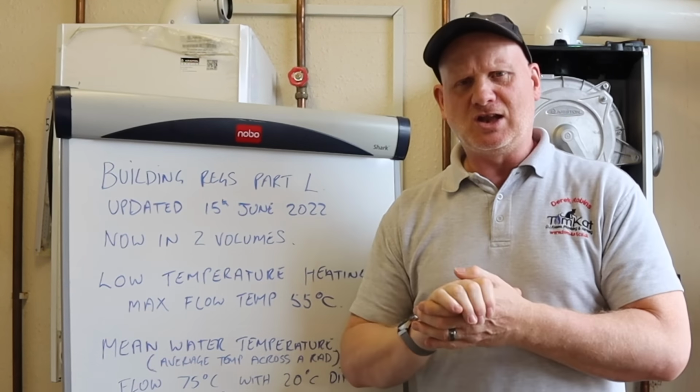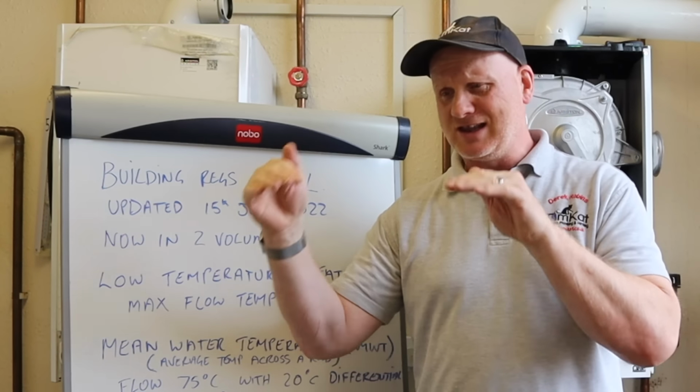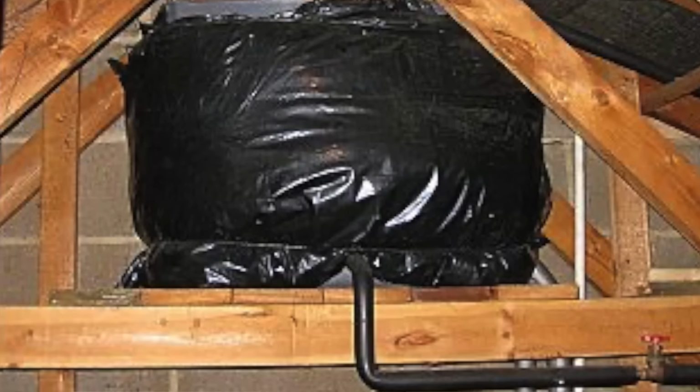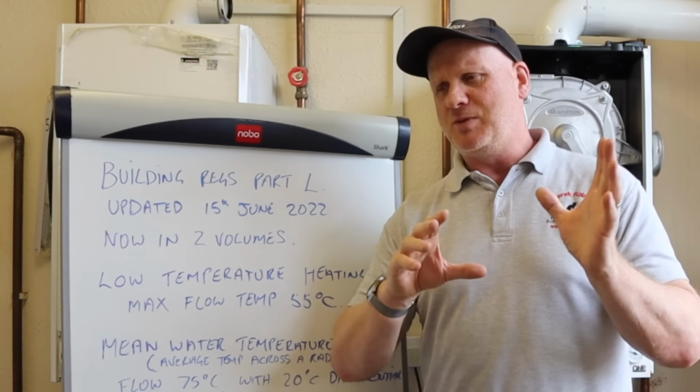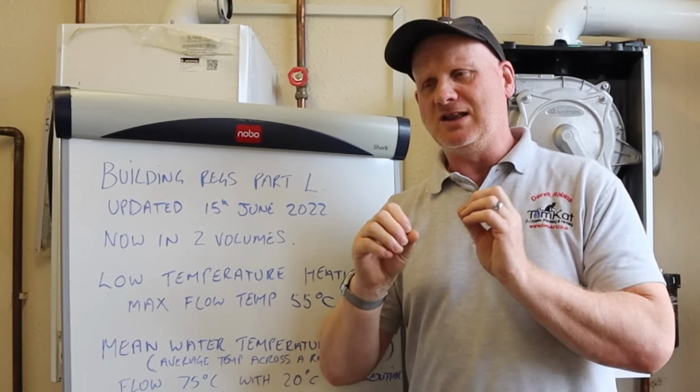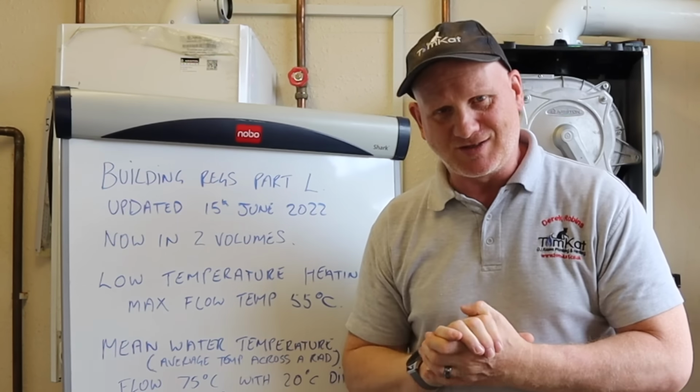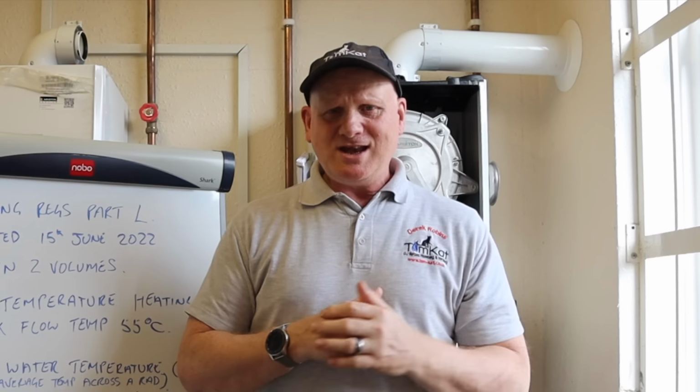Also, if you go up into your loft and you've got a feed and expansion system in there for your heating system, make sure that's got a lid on and it's well insulated and all the pipes are insulated, because again, as well as stopping it from freezing, you're stopping it losing heat in the cold areas in your loft. Big importance, insulation.